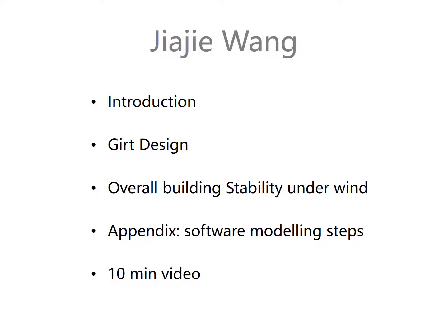In roof bracing design, the suction and pressure due to wind load on the windward and the leeward walls are important values. These values will be used when calculating the forces of the intermediate frame and forces of the end frame. The equal angles are also important because they will be used when designing all diagonal members. Only half the members need to be determined due to symmetry.